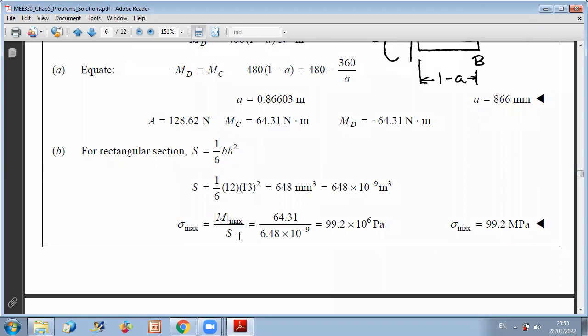And here, as we discussed before, since C1 equals C2, I just have to determine the maximum of the absolute value of the bending moment. I don't care if I have tension or compression, because C1 and C2 are equal. But if C1 and C2 are different, then as we discussed before, we should differentiate several cases. We should take the case of maximum positive bending moment alone and maximum negative moment alone. Here they are equal, because we designed it that way, but in general, whenever we have C1 different than C2, I should do several cases to determine which is the most critical one.